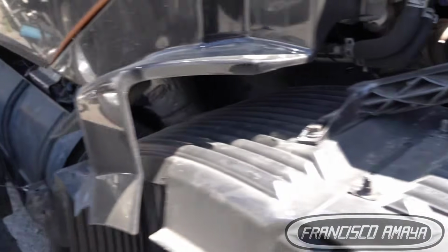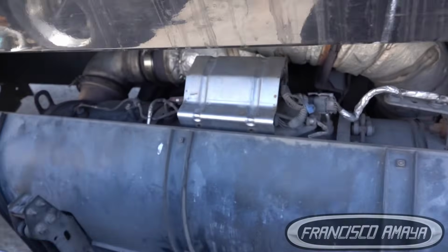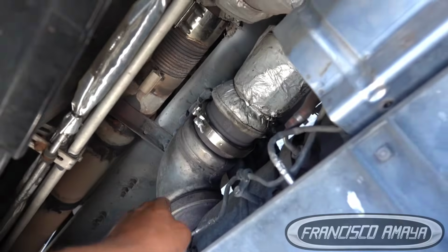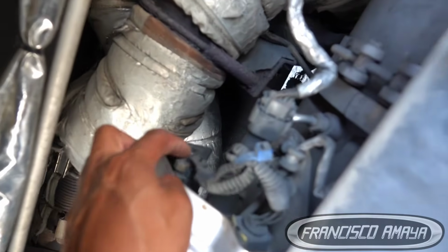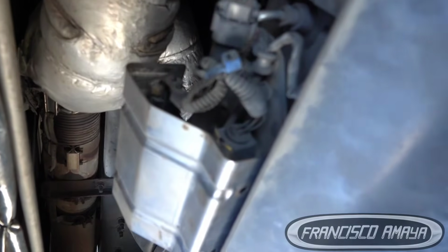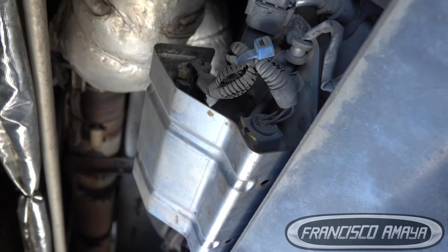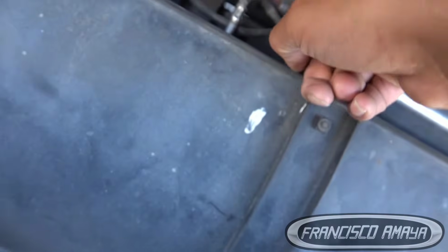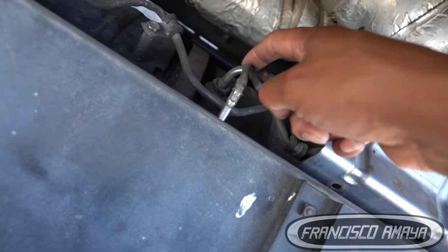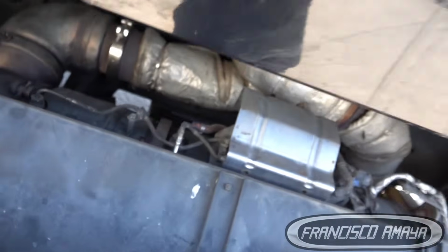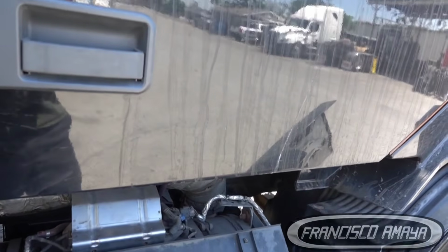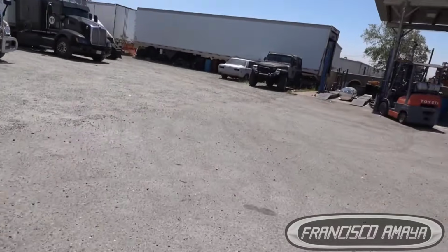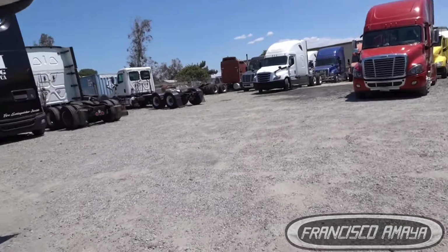And the other sensor location goes right here. This is the DPF filter. It comes from the engine. And this right here, the plug that you can see, is the differential pressure sensor. It then connects here and here, with those tubes right there. So what is the problem? That is what we're going to find out right now using the diagnostic software. We need to use that in order to find the problems.